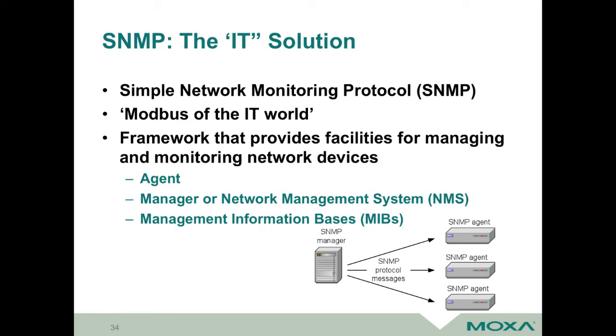Well, the IT guys do this. Some of you might know about Simple Network Management Protocol, or SNMP. I call it Modbus for the IT guys. And this is one technology IT uses, but not so friendly for us that are controls folks. It uses the concept of a manager, kind of like the SCADA server, and then the agents are software that sit on the edge devices to do that, okay? Good that it's out there. IT's been using it for 20-some years, works real well.